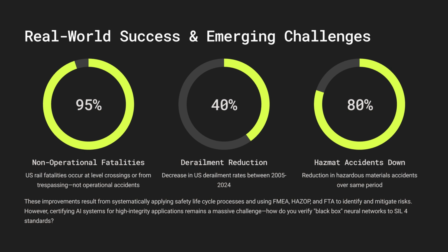Exactly. So Dubai Metro had to source and validate specialized fire detection systems. They used Hochiki sensors, for instance, which were specifically engineered and tested to work reliably and maintain high integrity, but have very low false alarm rates, even with high dust levels and ambient temperatures. You have to ensure your safety system is robust against nuisance trips in the specific operating context.